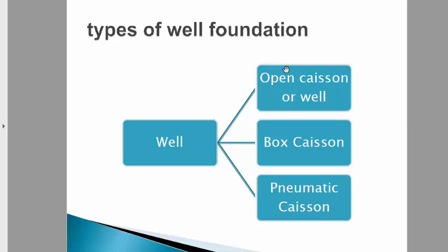What is important is, under what circumstances do we provide well foundations? First, if the load is large and piles are not sufficient to take that much load, we provide well foundations. Second, in the case of bridges, we provide well foundations. Third, in the case of a river where there is a water level, we provide a bridge and transfer the loads to the deeper soil. In these conditions we provide the well foundation.